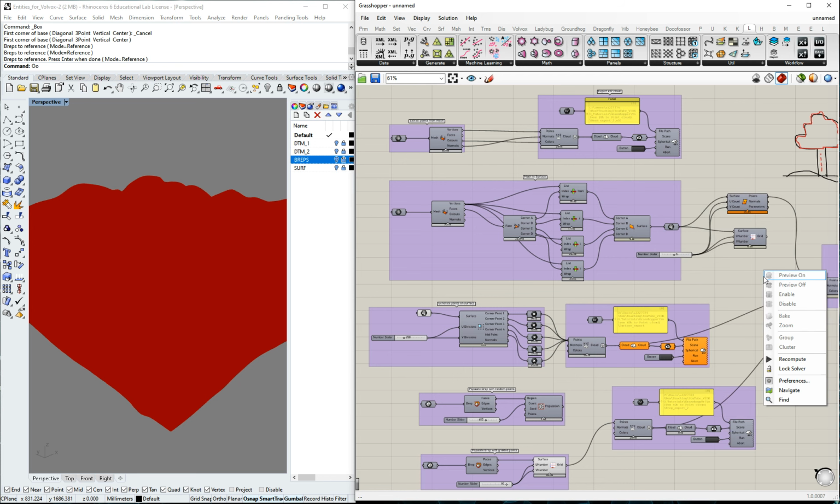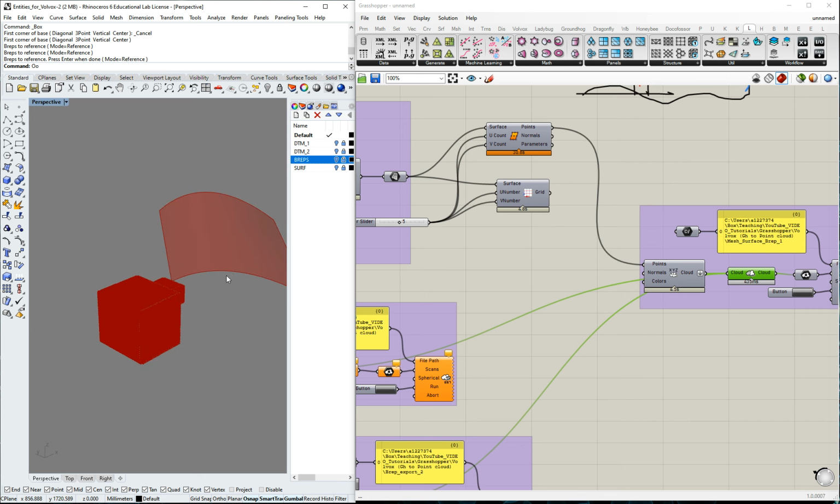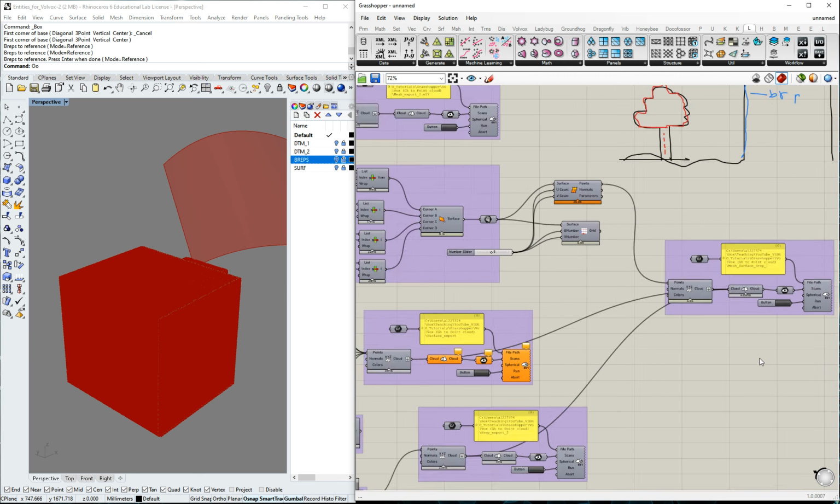And I hope you find this particular tutorial very useful. You practice at home and you try to represent different surfaces and export. There are other tutorials that I posted before about, for example, how to model everything using Elk. So I would really like you to try importing OpenStreetMap data using Elk or Urbano, generating the models and exporting all the breps as point clouds. So you're generating point clouds from OpenStreetMap, and that will be a very interesting workflow to explore.